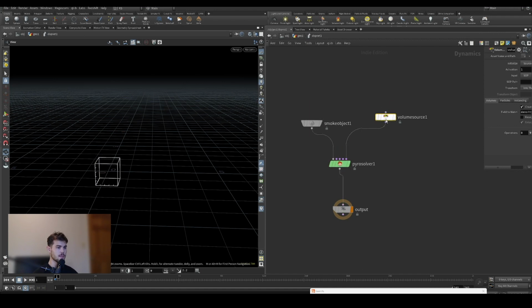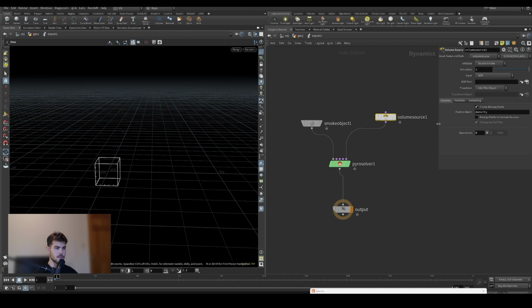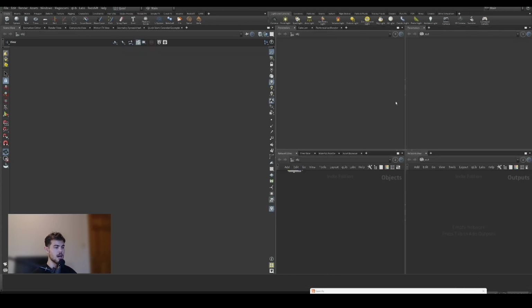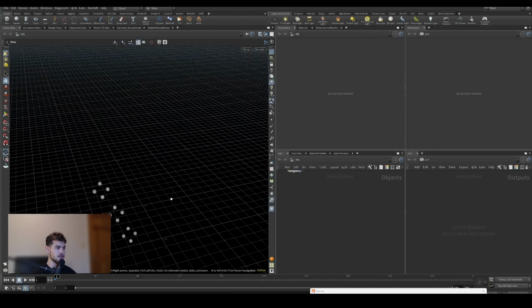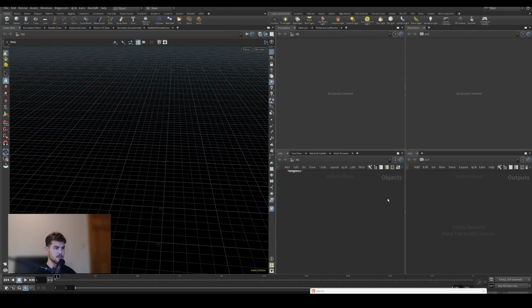If you're not familiar with using a quad view in Houdini, I think especially when you're working in DOPs, it's really useful. Basically it just means splitting up your viewport into four sections, and these two are linked and these two are linked. We can set the linking here, in the linking pane tab, this number 1 and this number 1 correspond to each other.